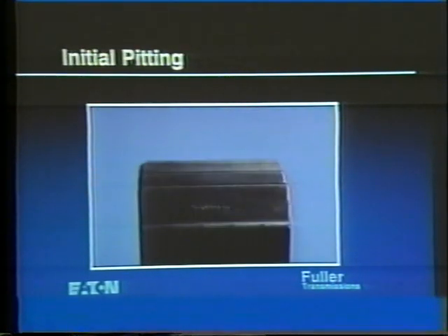Gear pitting is a surface condition which is normal in the early life of a transmission. It is the result of microscopic variations in the tooth form. The pit size will vary depending on the depth of the initial fracture. Initial pitting is the mildest stage of pitting. Generally, initial pitting continues until the tooth is able to carry the load without further distress. In many cases, it will heal over.